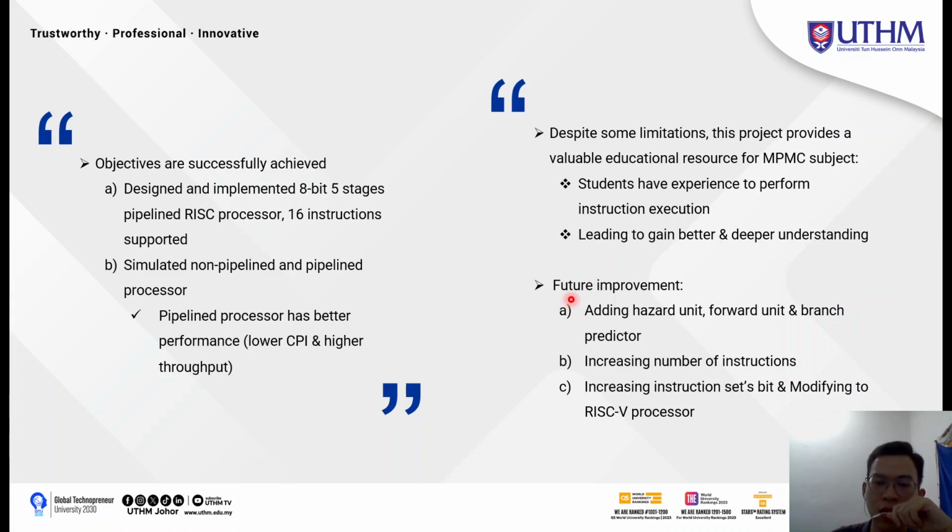For future work, the designed pipeline processor can be enhanced by adding a hazard unit, forward unit, and branch predictor to prevent hazards, and for better performance and faster instruction execution.